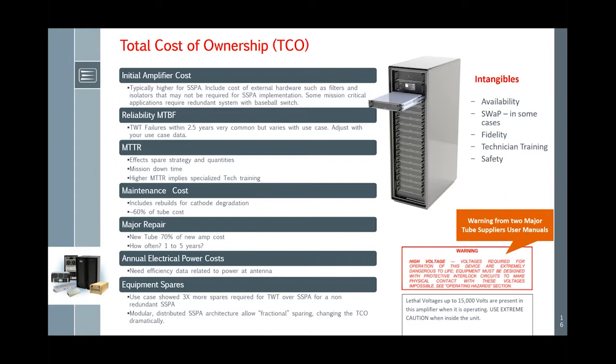The mean time to repair is not cost per se, but it's a driver of cost of ownership. It directly affects equipment sparing quantities, and higher MTTR implies more specialized technician service training required. Maintenance costs don't apply to solid state PAs, but they do for TWT, so you can fit that into your model.